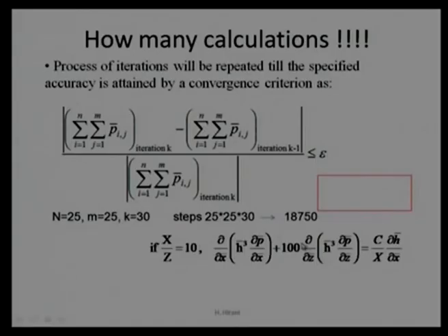It is more like a 99 times higher domination, obviously 99 times higher, not 99%. Then this term can be neglected to reduce the number of steps. And if we neglect this term, we require only nodes in z direction. We do not require any node in x direction as it is independent, and due to this, number of iterations will reduce.